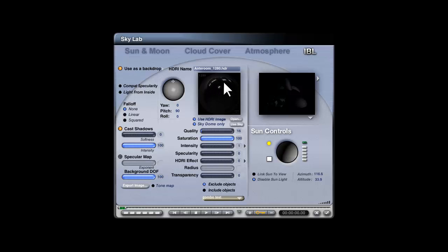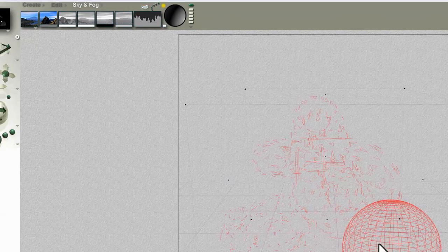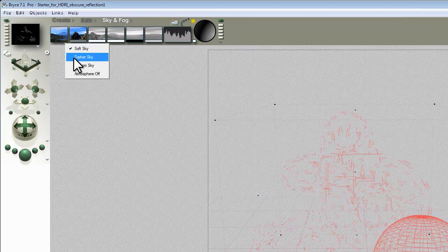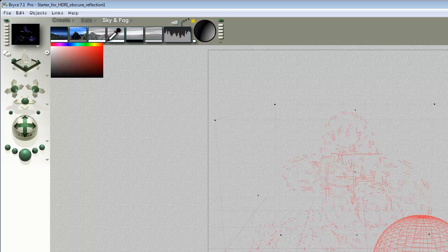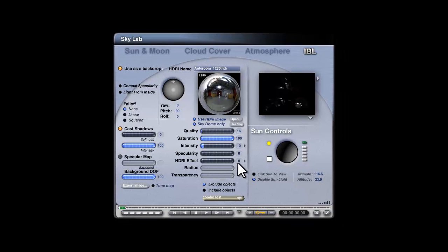I think you've already got a hint from there, because it's loaded in its old settings, that these fluorescent lights are the brightest part. Now if I take this intensity up to say 10, and we check that it's added to the sky, and I'll just check out of here. What I'm going to do is make sure the sky is set to fully black, so we're only adding in the HDRI backdrop. We've got no light output from this, so we're only looking at reflections at the moment, and I'll just give this a quick render.